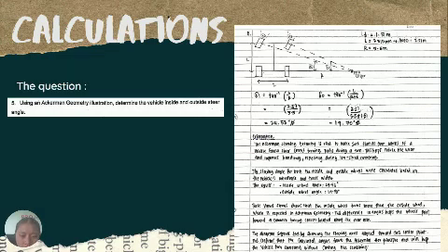this value shows that the inside wheel turns more than the outside wheel, which is expected in Ackermann geometry. This difference in angles helps the wheels point toward a common turning center located along the rear axle. The diagram supports this by showing the steering axes aligned toward this center point. This confirms that the calculated angles follow the Ackermann principle and will help the vehicle turn smoothly without causing tire